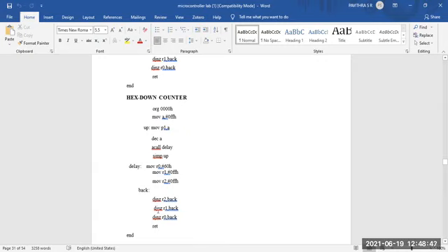Why are we doing decrement R2, R1, R0? It should become 0. When it becomes 0, it will start counting the value. DJNZ means decrement jump if not zero. Till it becomes 0, it will keep on executing the program. Let me execute and show this program also.